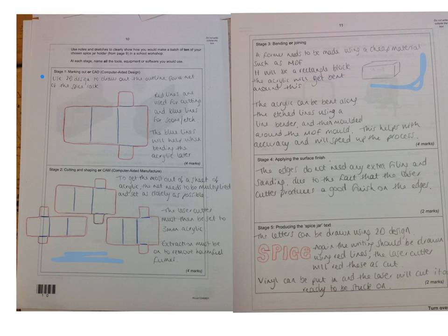And then the lines that you etched on earlier in blue are the lines that you will bend it along, using a line bender, a strip heater, those sort of pieces of equipment, to make sure that the acrylic is bent at the right place. I've then given a little benefit of using a mould to do this. This helps with accuracy and speeds up the process as well.